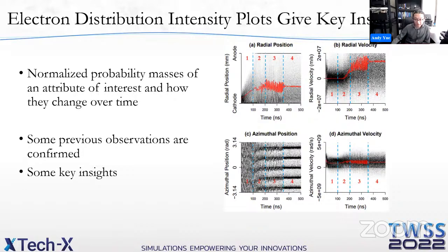The azimuthal position plot is unique since the azimuth of the cylindrical geometry forms a complete circle. So the bottom of this plot is actually connected to the top of the plot. Since the time step delta t is exactly 1/1000th of the RF period, and electron data was dumped every 1000 steps, electron data was dumped at the exact end of every RF period in this case. Therefore, if the device is indeed oscillating in the pi mode, the azimuthal position plot should have 5 perfectly horizontal lines. Deviation from these lines indicates frequency instability.